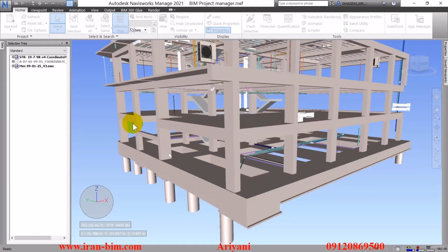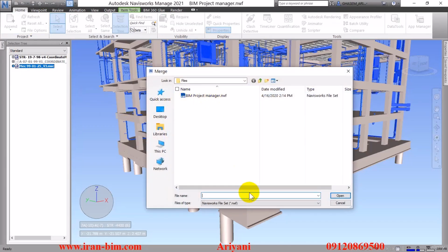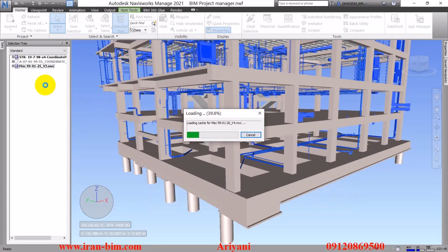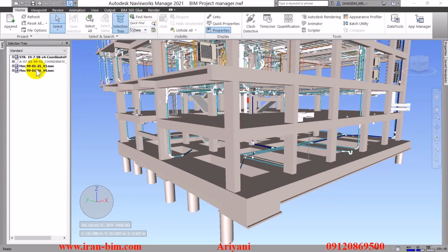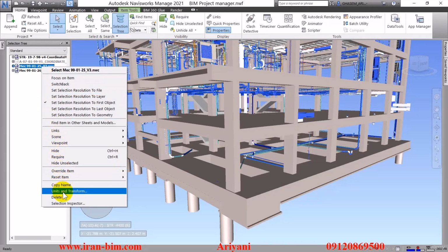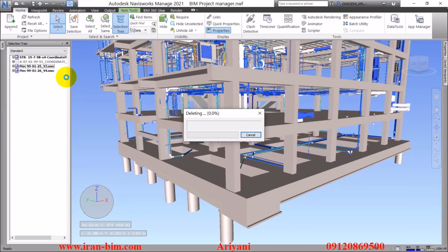We can go over here and first select the append option, open this up and select merge. Alright, and now in the browser we can select version 4 of the mechanical file and open it up in the project. Now you can see it's added here with its own unique design. So now I'll select and delete version 3 of the file because it's not in use right now, and we could have hidden it as well, but I just didn't want the file to get too heavy.